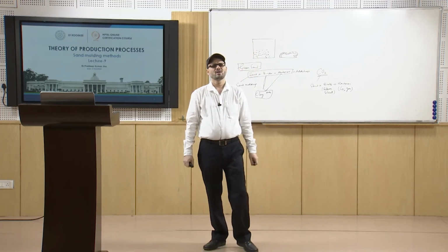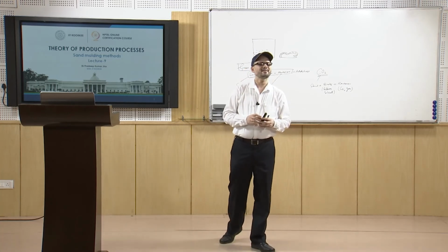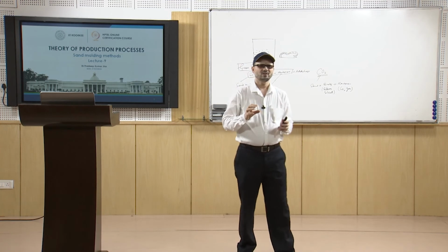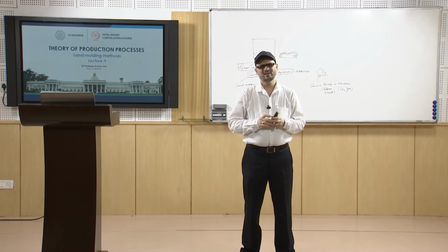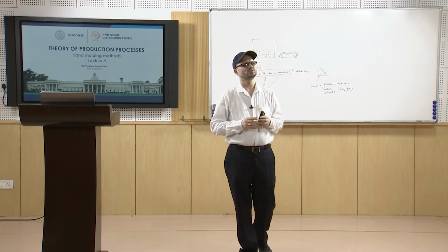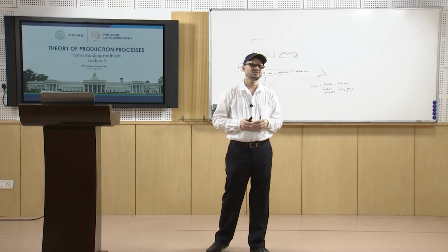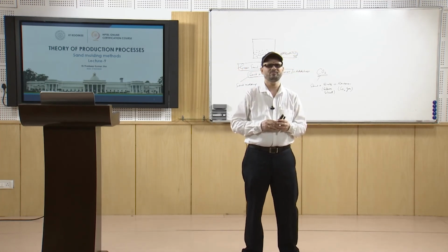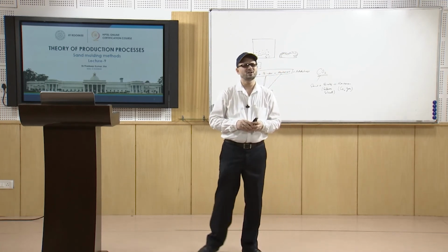So, that way it has two varieties, one is hot chamber and another is cold chamber die casting. Normally, die casting is used for low melting point materials. It is not considered suited for ferrous materials. Normally non-ferrous materials are cast, lower melting point alloys like tin, lead or zinc. So, these are the materials which are used.